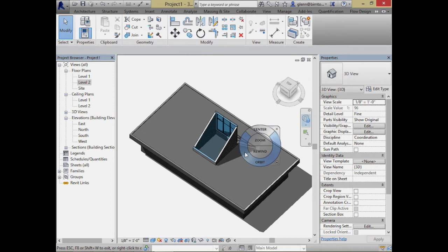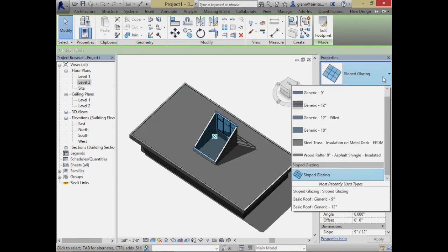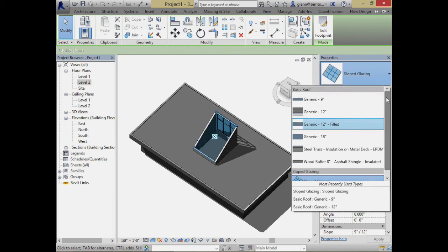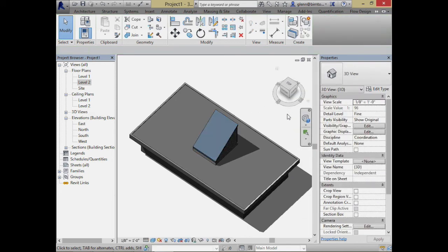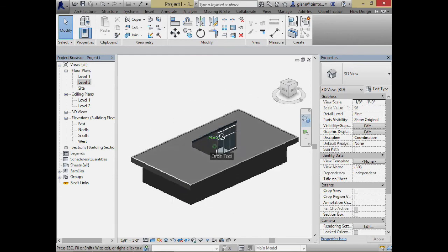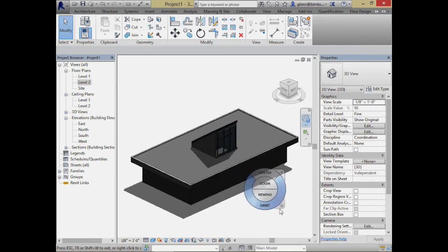So if you want to control that, what we can actually start doing is thinking about mixing up the materials. So instead of that being glazing, maybe that is even a solid surface, and instead you just have glass on the one side. Let's talk about the advantage of that, or why that's useful. So in this scenario, I have the glass just facing the north side. I have no glass facing the south side. Okay, so what does that give you?